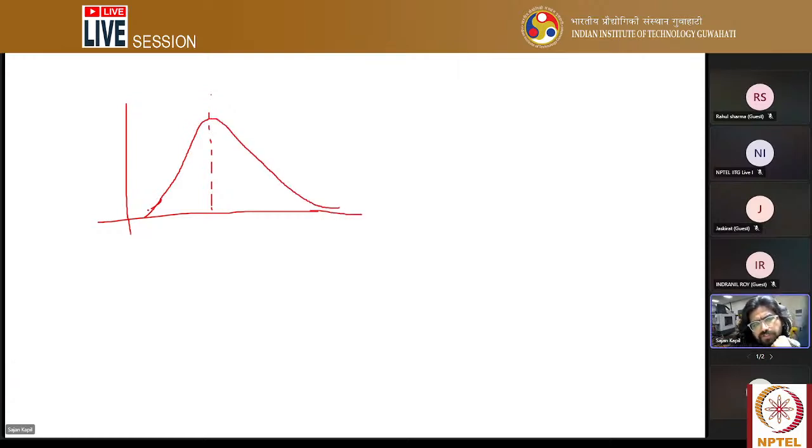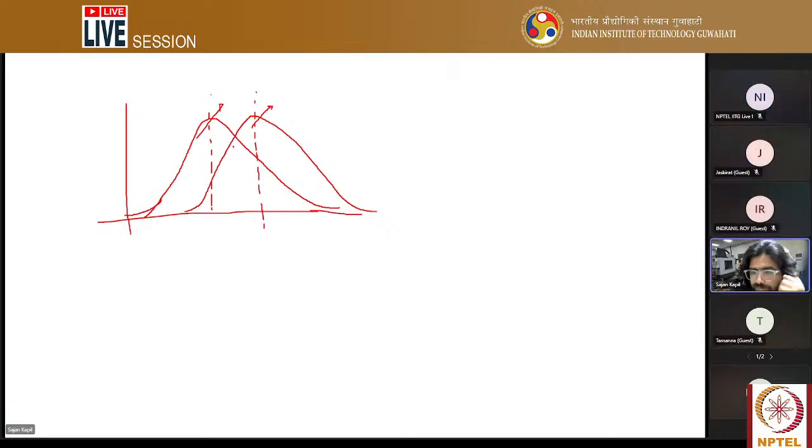That will be a nice Gaussian distribution. Then K is nothing but the percentage of the overlap. For example, the next pass is falling here, which means the peak will be here, and that is how it is going to make the next laser pass. The pass is in this direction. Now at this location, the energy given by the left one and the right one are going to add up.